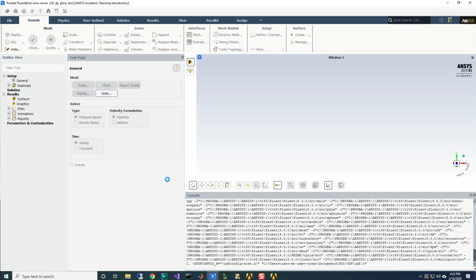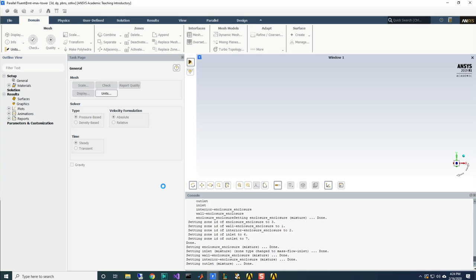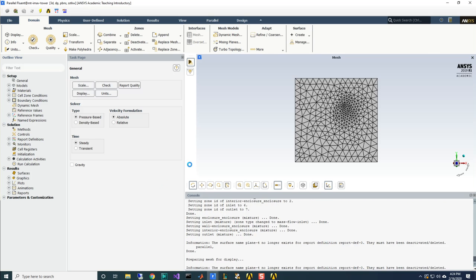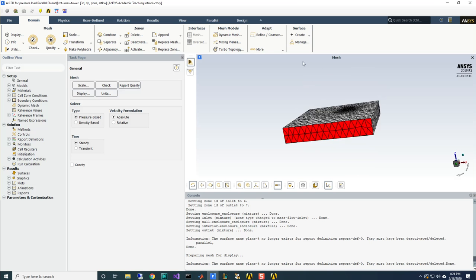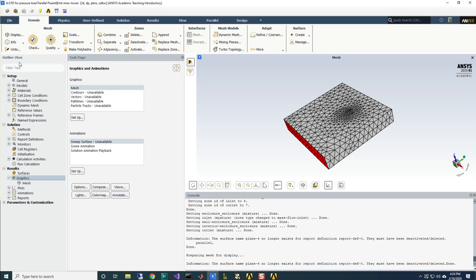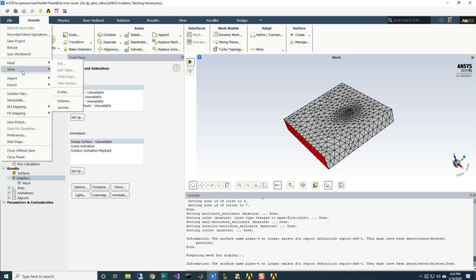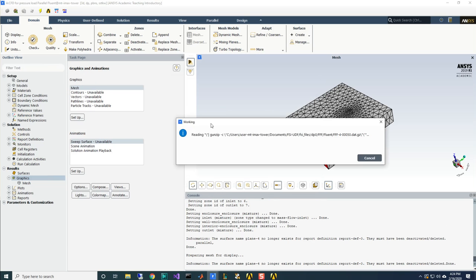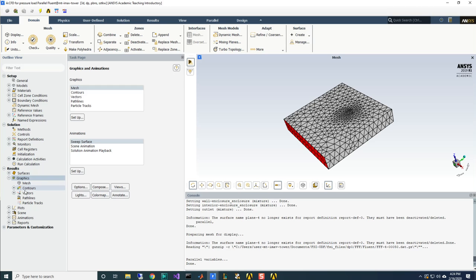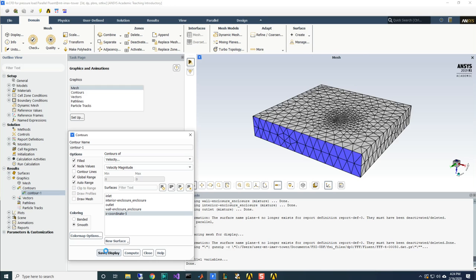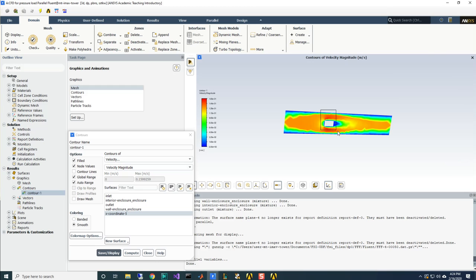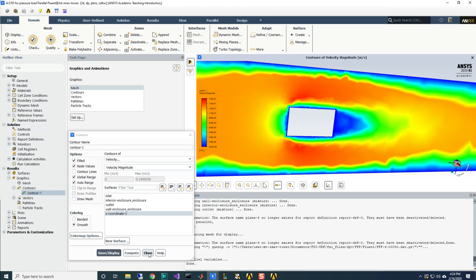And just like with the transient structural, where we didn't need the solid and we suppressed it, in creating our fluid mesh, we do not need the surface body, so we're going to suppress that. And I'm going to generate a mesh on this real quick. I like to use, in an application like this, the multi-zone mesher. I'm going to tell it to sweep from the top here. And to get a nice mesh, I'm going to insert a face meshing on that.